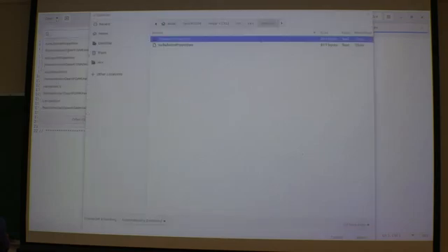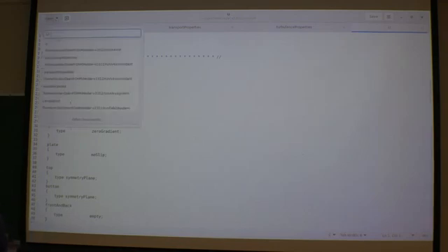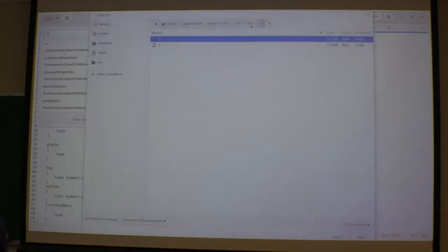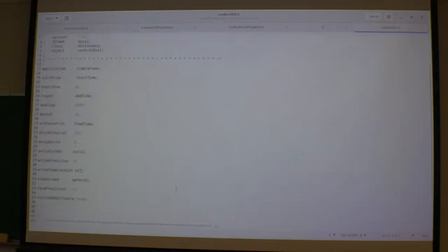And then, just to make sure we don't do anything wrong here, velocity. Yes, I send in 1 meter per second for the inlet, and the rest should be standard. Nothing strange here. And in my control dict, it should read simpleFoam, I start from 0, and I have maximum 2000, nothing strange here, and no functions.